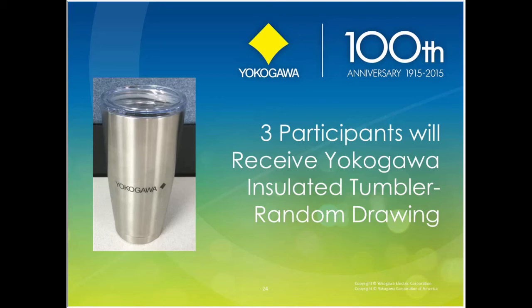Robert Bland asked a good question. Does the thermal well affect the temperature or accuracy? It's going to affect the accuracy a little bit, but not significantly. The main thing is it's going to affect your response time. That's the big consideration when you're doing thermal wells, you really have to be okay with the higher response time. If it's a critical application, maybe for safety, where you need a fast response time, there are various thermal well options that can get you a better response time, but you always need to be aware of that.